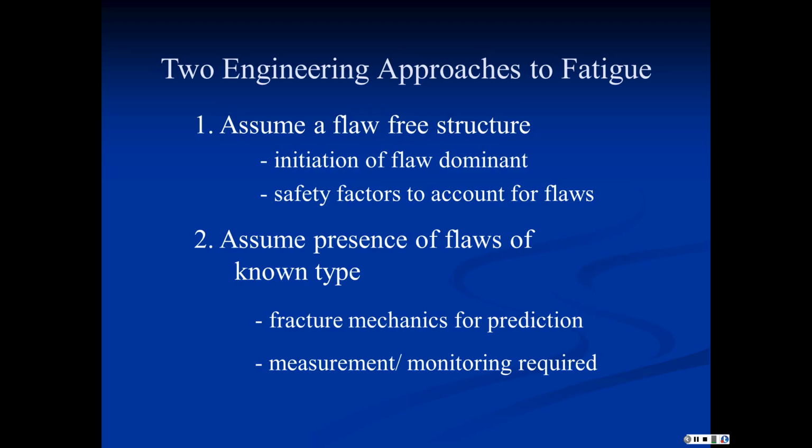Now, as we approach the problem of fatigue, if you remember back to failure, just 2 lectures ago, we pointed out that there's 2 stages in any failure, that all components that break into 2 or more pieces have experienced crack growth. But cracks don't just appear. There's an initiation process, which is usually dominated by a particular set of mechanics issues. And then there is propagation, which is often controlled by different things than the initiation process.